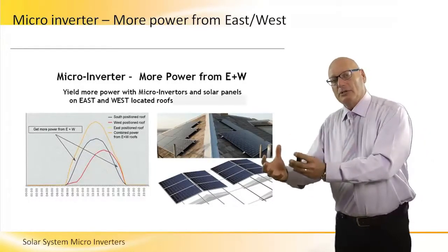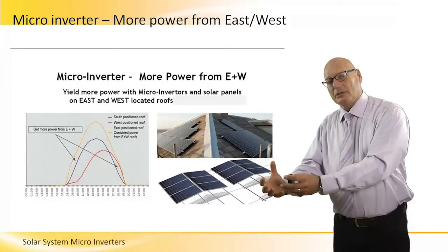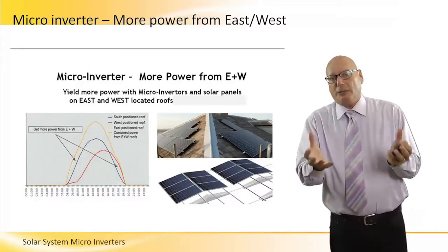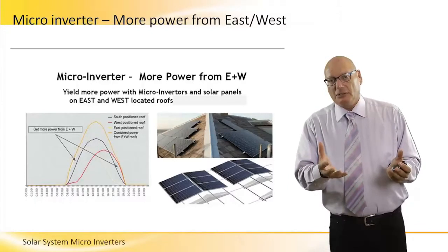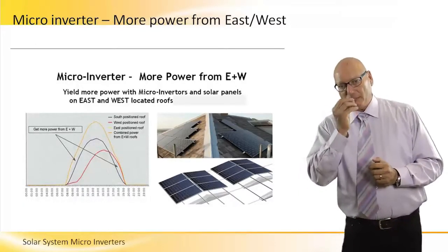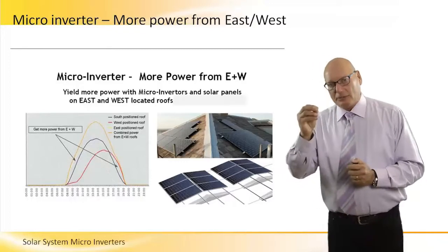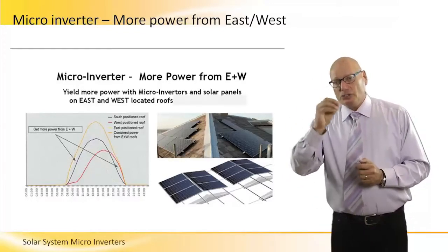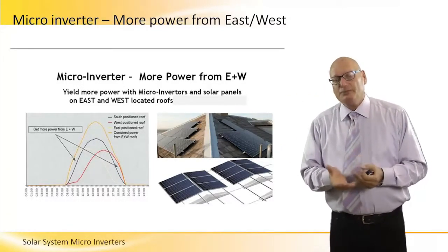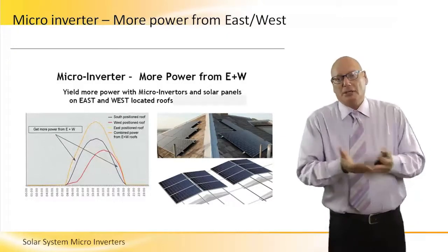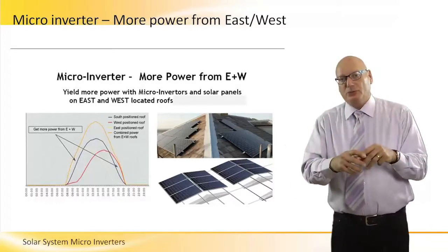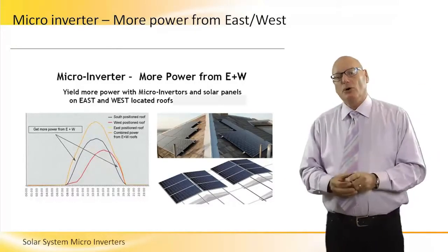So we capture sunlight early in the morning, we capture sunlight late afternoon, and obviously, we capture the sunlight during midday. The combination of all these increases the power. So the fact is that the microinverter has an MPPT circuitry, again and again assuring the multiplication of I times V is at the maximum. This allows us to place panels looking to the east and to the west, still receiving a lot of energy, combining it with panels looking at the south, together to get more power.